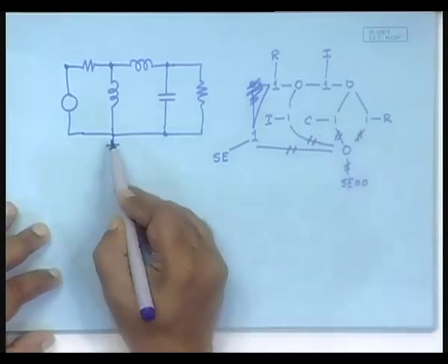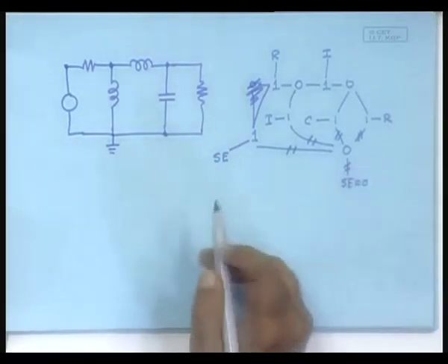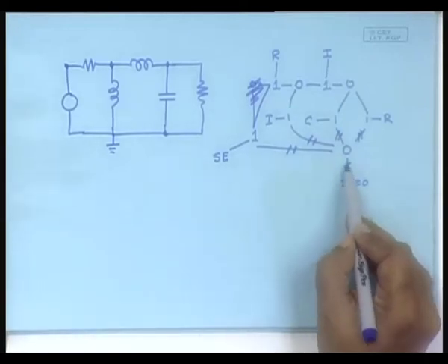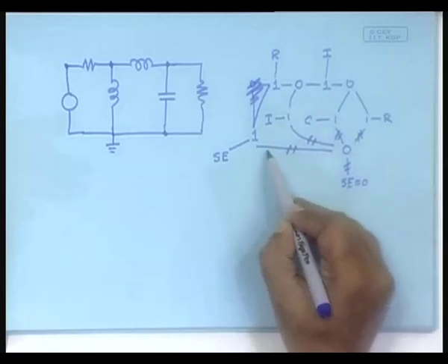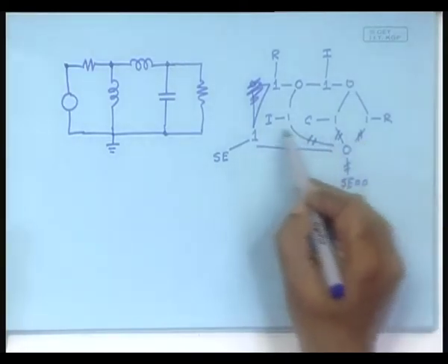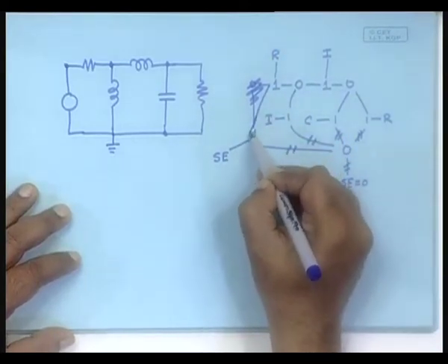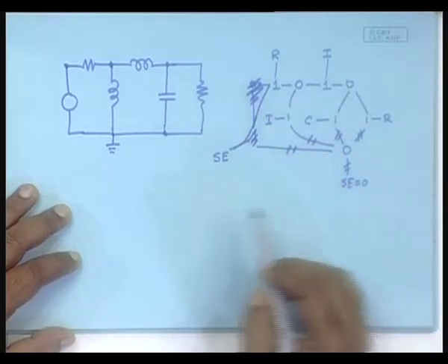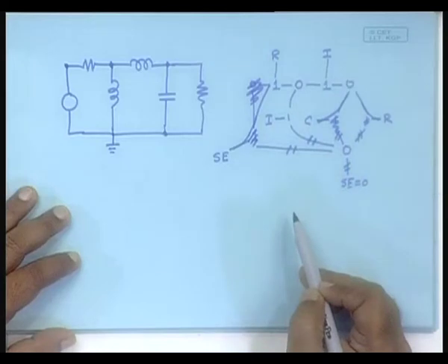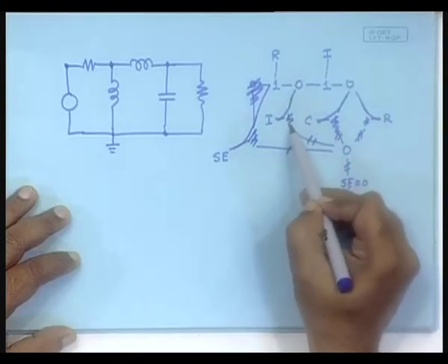We always say that one of the voltage points or nodes would be at 0 potential. There is no harm in doing that. That is a datum, and the moment you do that, in the bond graph that is reflected as the SE becoming 0, and the SE being 0 and connected to a 0 junction means all these bonds will carry 0 effort, therefore 0 power, because the power is effort multiplied by flow. So, all these are unnecessary. Now we see that this again becomes a through junction, is unnecessary, this is also unnecessary, fine. This is also unnecessary, we can connect it, this is also unnecessary, we can connect it. Is there anything else? Okay, this is 0, therefore this has become unnecessary, this can be connected.